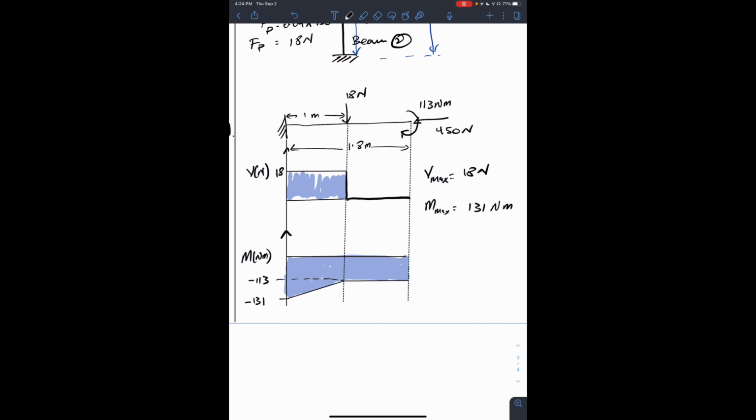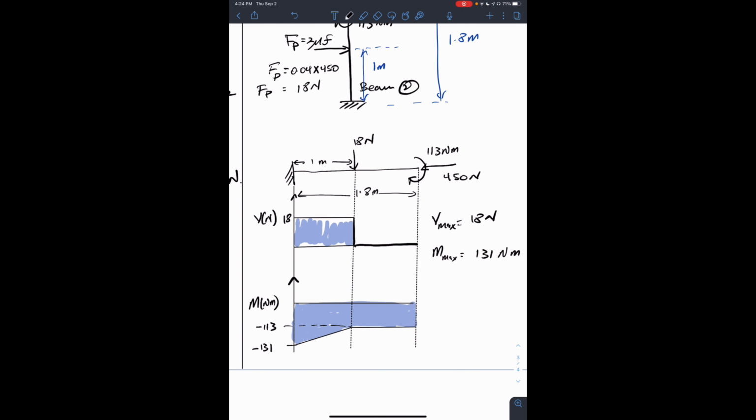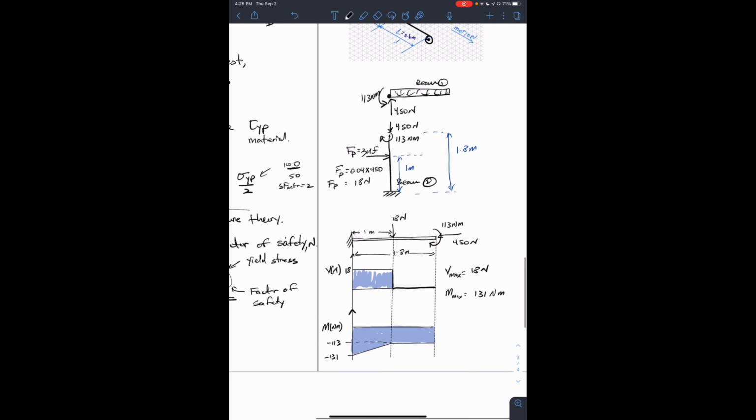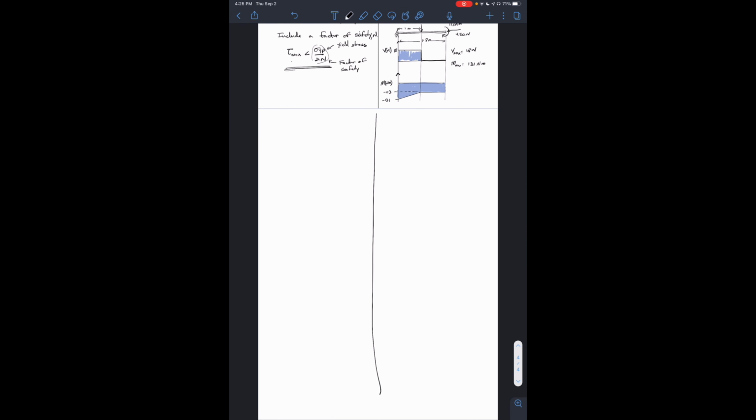Right, so we have the negative sign here, but the negative sign would mean that as the beam is bending, right, so this is the beam here, as it's bending down, the bottom will be in compression, the top will be in extension. Right, so in this case now it is important that we try and visualize that. So I'll talk a bit about that now.